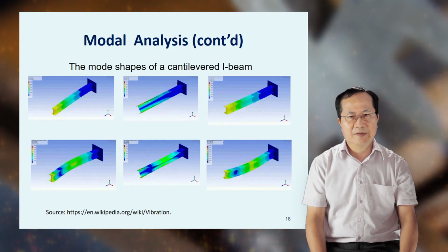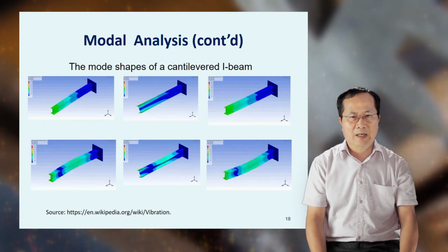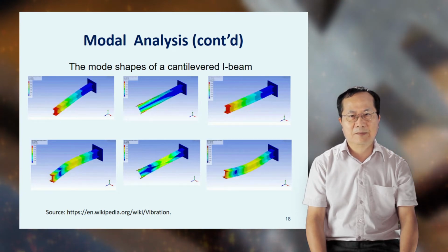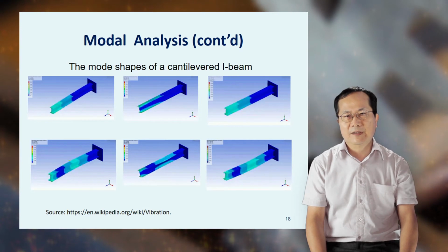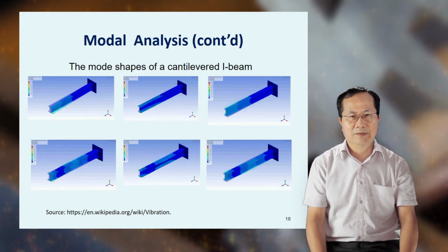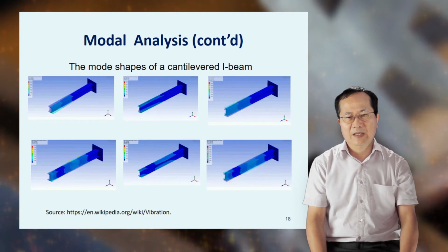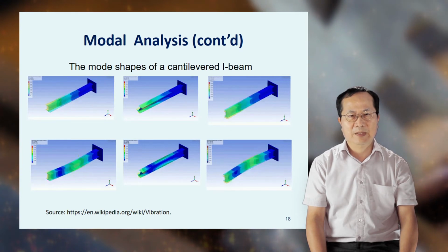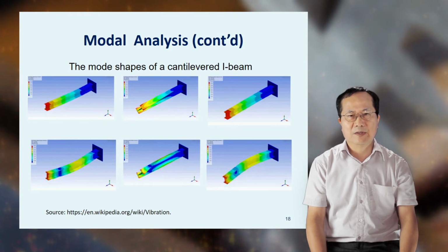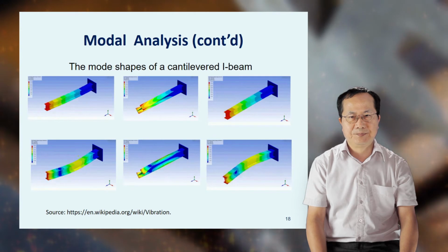Therefore, the relatively simple model that has over 100 degrees of freedom, and hence as many natural frequencies and mode shapes, provides a good approximation for the first natural frequencies and modes. Generally, only the first few modes are important for practical applications. In this table, the first and second horizontal bending, torsion in the middle, and the vertical bending in the right vibration modes of an I-beam are visualized.